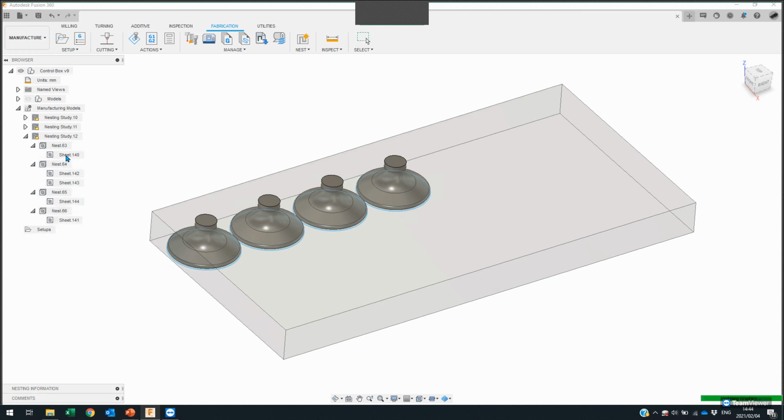And for each material type, there is then a sheet output for each material. So you can see for 64, I've used 2 sheets of material there. And Fusion is just busy calculating and generating the nested result. So I'll just give that a second to do that. While it does that, unfortunately, Fusion is somewhat locked, so I won't be able to browse through anything here.